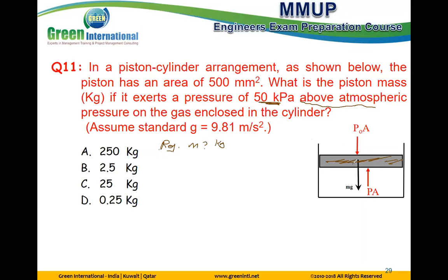The weight of the piston itself, mg, and the force due to atmospheric pressure from outside. Also, we have a force coming from inside the piston, because inside the pressure is 50 kilopascal.